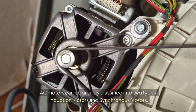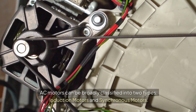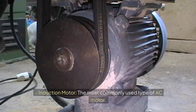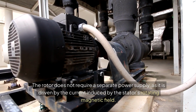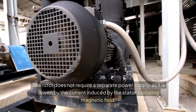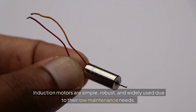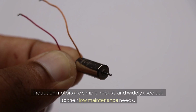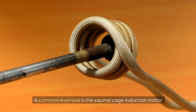3. Types of AC motors. AC motors can be broadly classified into two types: induction motors and synchronous motors. Induction motor, the most commonly used type of AC motor. The rotor does not require a separate power supply, as it is driven by the current induced by the stator's rotating magnetic field. Induction motors are simple, robust, and widely used due to their low maintenance needs. A common example is the squirrel cage induction motor.